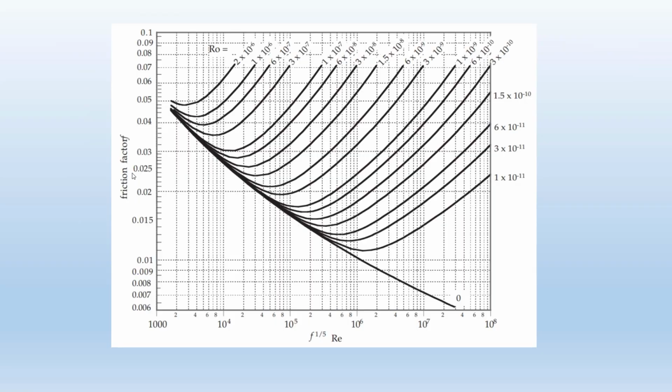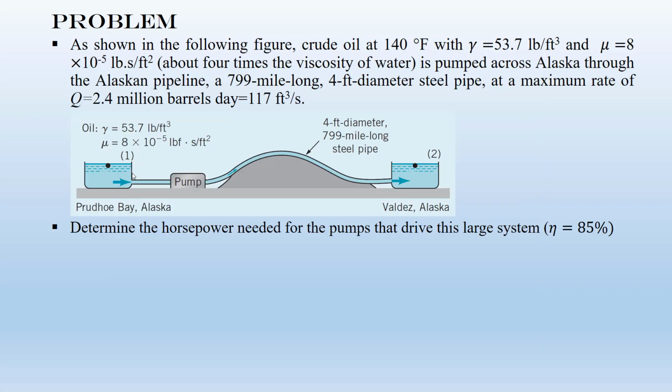So here, guys, in this part, we just studied 3 different types of problems for a single pipe. The first one was when the pressure drop was unknown. It's straightforward; you can simply calculate the unknown parameter, the pressure drop. The second type is when the velocity is unknown, and the third one is when diameter and velocity are unknown. Okay, let's solve 2 problems from this section, and then I will go over non-circular pipes.